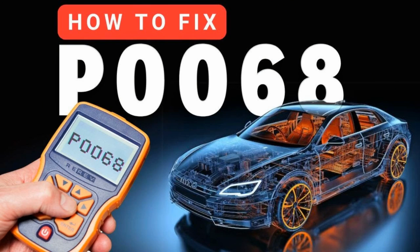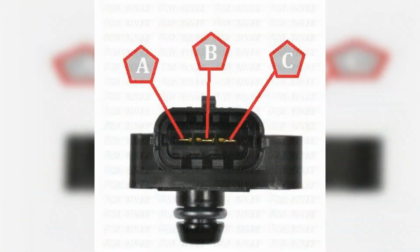How to diagnose P0068? If your analysis tool displays a P0068 code, take your vehicle to a reliable auto repair shop and ask an experienced mechanic or technician to examine it. However, if you have the skills and tools to diagnose it yourself, here are some diagnostic steps you can try to understand the underlying problem. Check for leaks or loose clamps in the piping from the MAF sensor to the throttle body. Inspect MAP, MAF, and throttle position sensor connectors for corrosion and other visible problems. Start the engine and test the intake manifold for leaks. Check for signs of coke, a dark, oily material inside the throttle body. Run tests on each sensor to make sure they're all working properly.